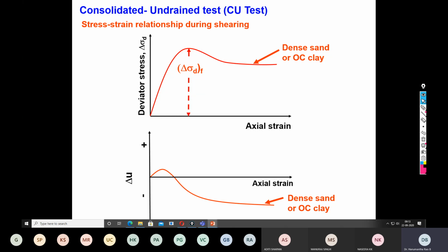In the case of negative, this pore water pressure is also called suction. The capillarity, the suction within the soil sample, is so high that it could absorb a lot of water. While when the pore water pressure is positive, it could not take more water, since water is already within the sample. So the sample doesn't show any affinity to absorb water.